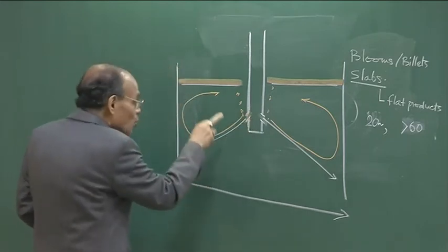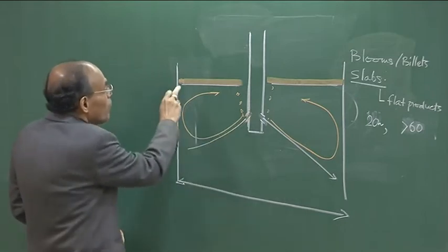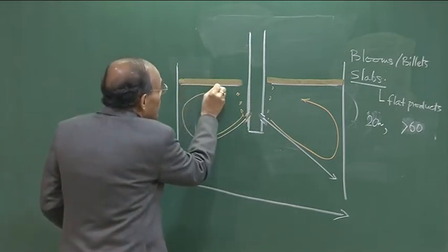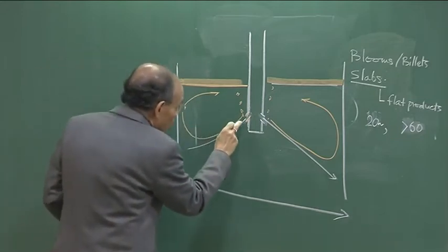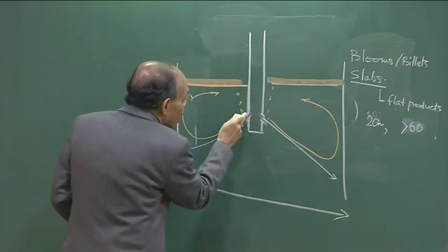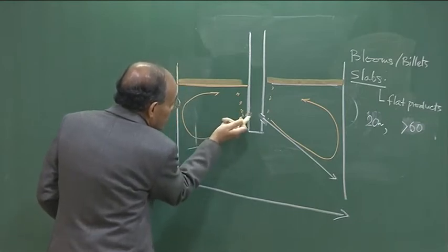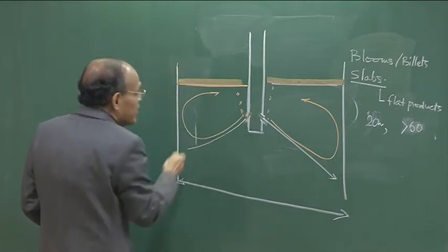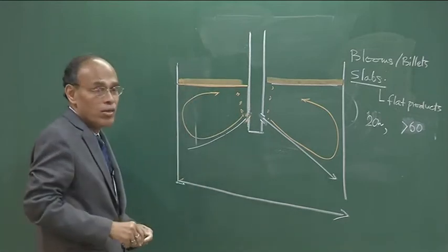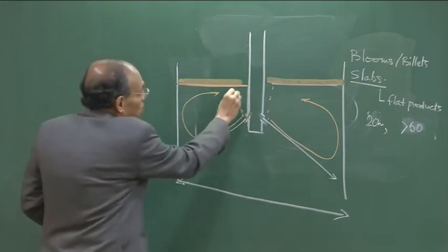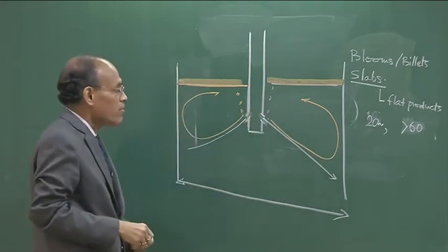More than the requisite amount of taper will produce a cold slag metal interface. Similarly, less than the required amount of taper, that means if the port is horizontal or upwardly directed, that is what I mean, in that case the disturbance in the slag layer could be so enormous that droplets of slag could be entrained in the system itself.